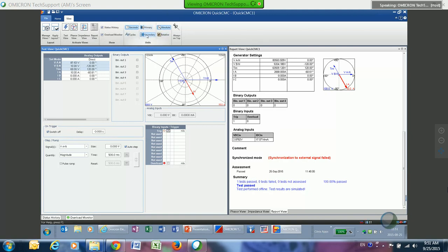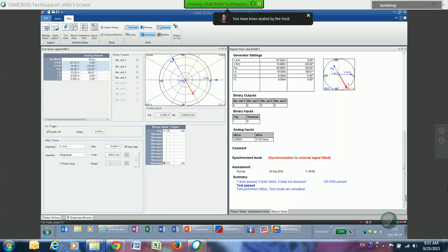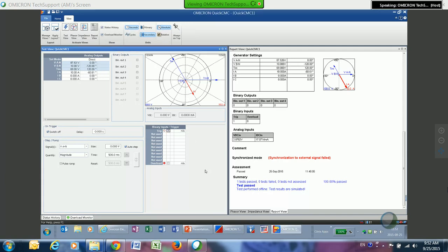And a lot of times if I'm doing reclosers or even relays, maybe I want to see these values as primary values because that's what it shows on my metering. And then I could come and choose this window, and it's just easier for me to look at the values instead of getting a calculator out and calculating the values that I want to see. Then I can select absolute and relative out here. Usually it's just defaulted to absolute values.